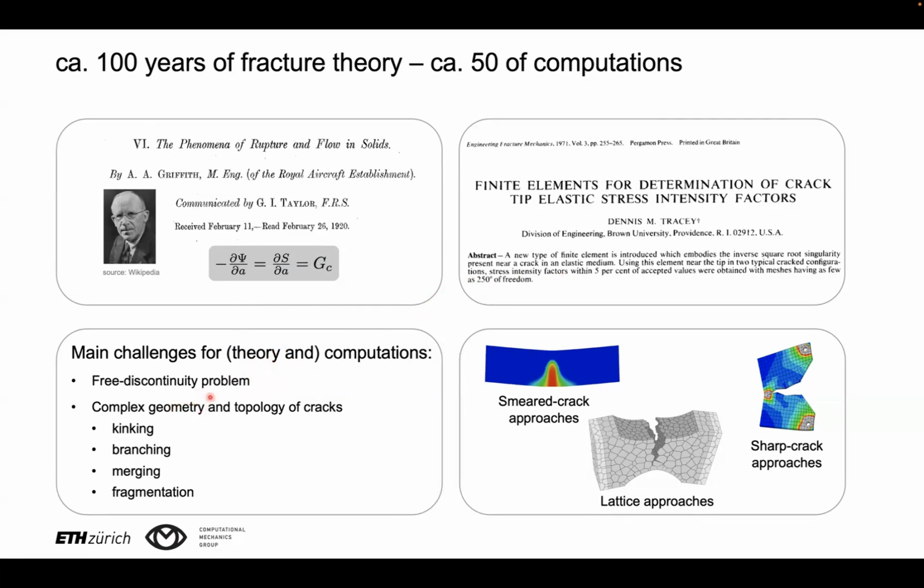One of the reasons is that this is, mathematically speaking, a free discontinuity problem. So where there's a crack, there's a discontinuity in the displacement field, which is the field we solve for in mechanics problems. And we don't know upfront where the discontinuity occurs because we don't know upfront where the crack is, which is why we call this a free discontinuity problem.